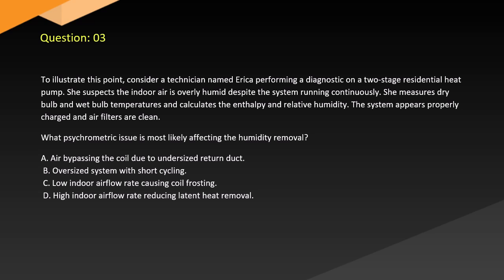Question 3. To illustrate this point, consider a technician named Erica performing a diagnostic on a two-stage residential heat pump. She suspects the indoor air is overly humid despite the system running continuously. She measures dry bulb and wet bulb temperatures and calculates the enthalpy and relative humidity. The system appears properly charged and the air filter is clean. What psychrometric issue is most likely affecting the humidity removal?